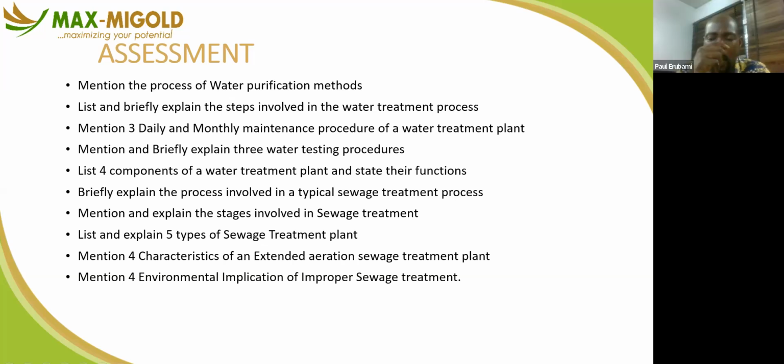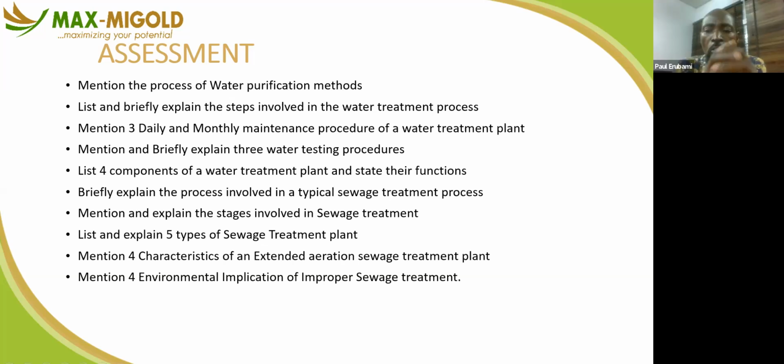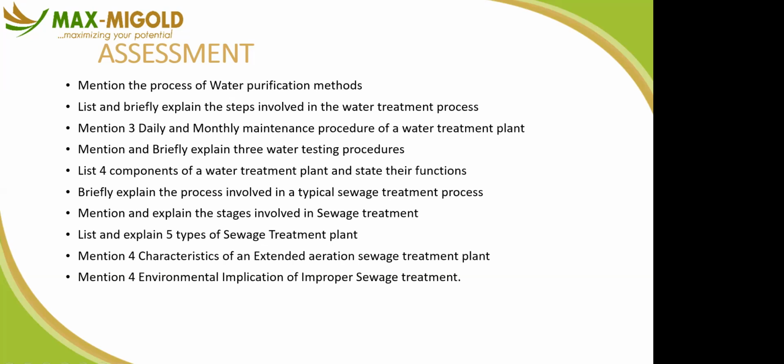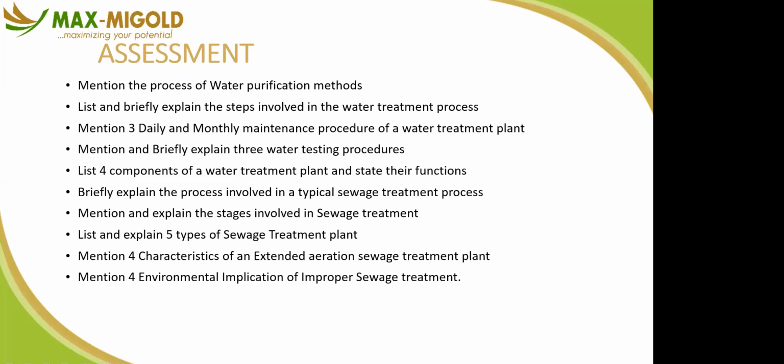No, when you don't have enough yield in your borehole, there are two things you can do. You can flush the borehole with chemical. There are several chemicals you can use to flush the borehole. Those are done by borehole experts. After you have flushed the borehole and the yield is still not okay, you can do what we call compression. You can get a compressor and compress the borehole.